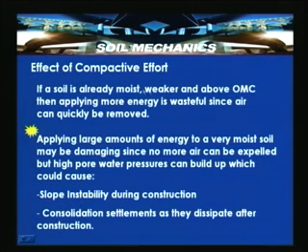If a soil is already moist, wetter than OMC, then applying more energy is wasteful, since air can quickly be removed. Applying large amounts of energy to a very moist soil may be damaging, since no more air can be expelled, but high pore water pressures can build up. That is what we have discussed. This could cause slope instability during construction, or consolidation settlements as they dissipate after construction. These pore water pressures, developed by applying energy to already wet soil, are locked in the soil, which actually causes instability to the structure.